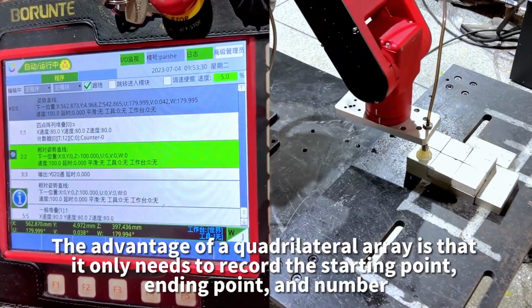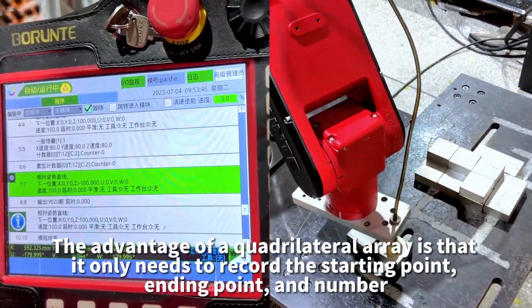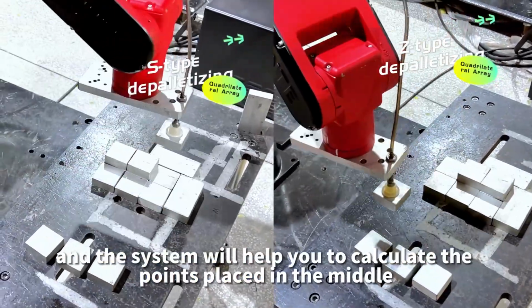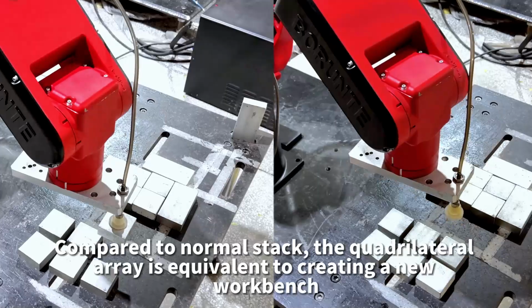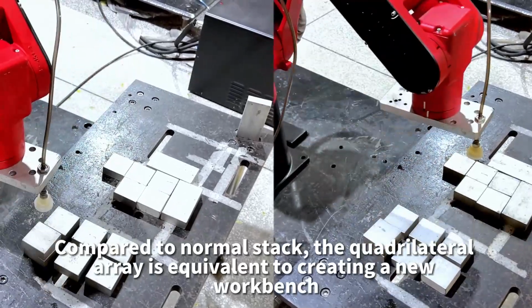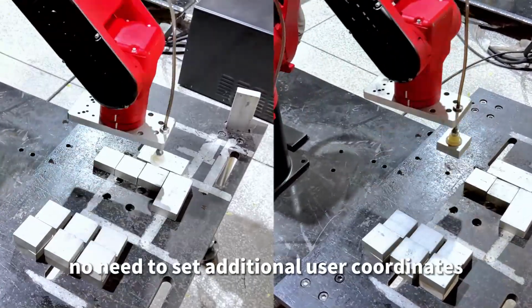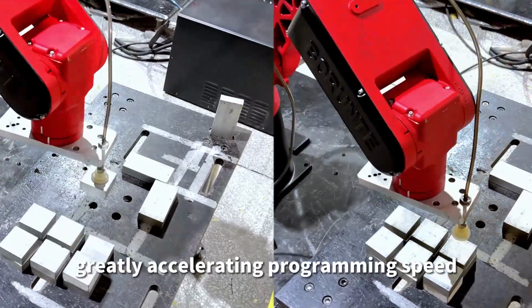The advantage of a quadrilateral array is that it only needs to record the starting point, ending point, and number. And the system will help you to calculate the points placed in the middle, greatly reducing programming difficulty. Compared to normal stack, the quadrilateral array is equivalent to creating a new workbench. No need to set additional user coordinates, greatly accelerating programming speed.